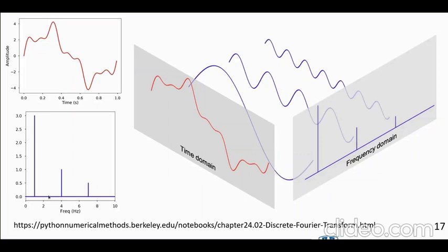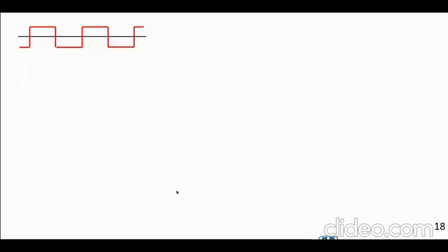In the frequency domain it's just three spikes. This is why when you have an FFT analyzer or instrumentation, you can ask it to take a signal that's coming out of an accelerometer, perhaps, and show it to you in the form of a time history, which may be totally useless, or in the frequency domain, which may be some spikes. Now, in real life, these spikes are not like that. They're going smoothly up or smoothly down, with a bunch of jagged stuff here, smooth up, smooth down, etc. So you've got to be careful.